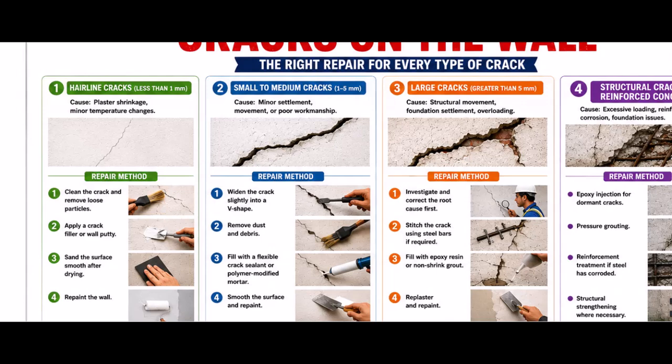Let's look at the final kind of crack, which is the structural cracks in reinforced concrete. The cause of this crack is excessive loading, reinforcement corrosion, and foundation issues.